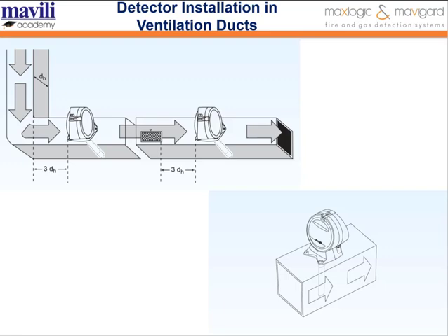Now, where should these detectors be installed? The first location is at points where the airflow direction changes, such as after a bend in the duct. For example, when the airflow moves horizontally and then changes direction at a corner, like there.